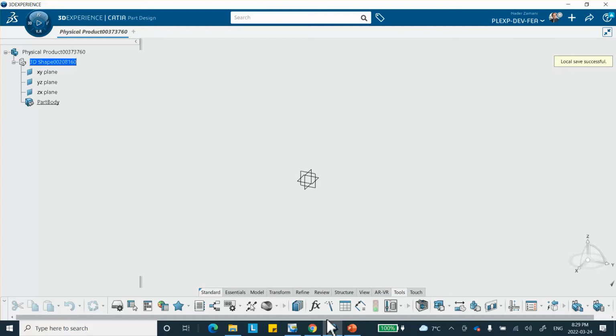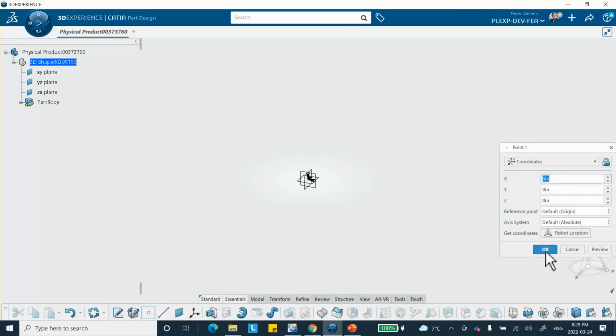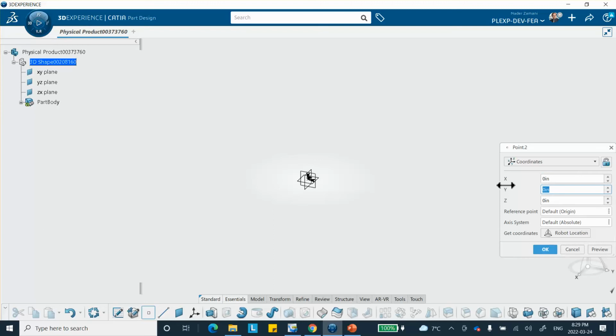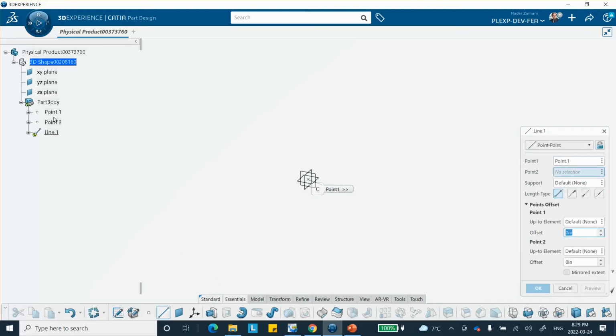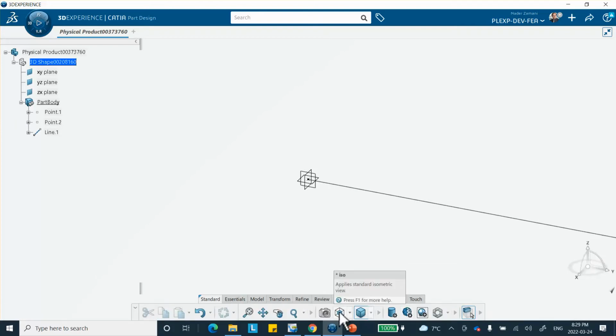It's a very simple geometric model. It's just a line which is bounded by 2 points. So let's go ahead and create 2 points first. One of them is the global origin. The other one is 200 inches away on the y-axis. Okay. And now here are the 2 points that are created. I can create a line between these 2 points, between this point and that point. And if you want to see it, just make sure you fit it. The fit under view, there's the fit.